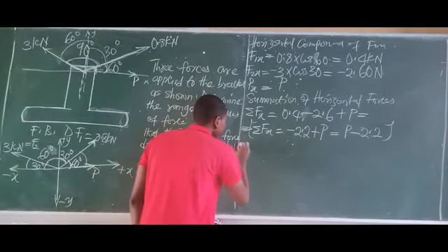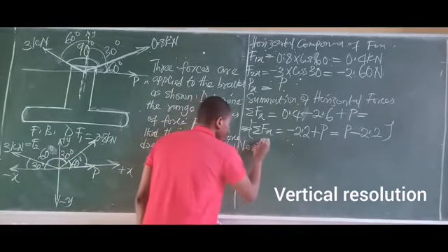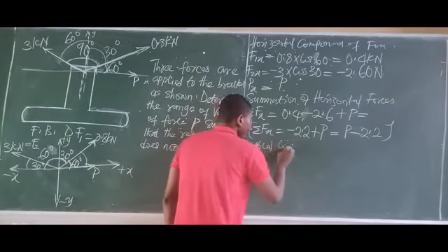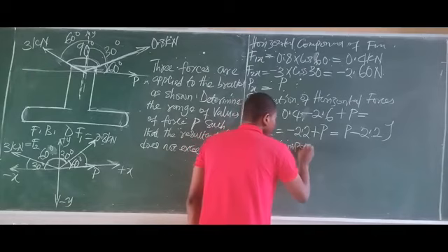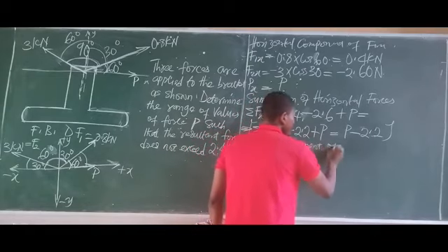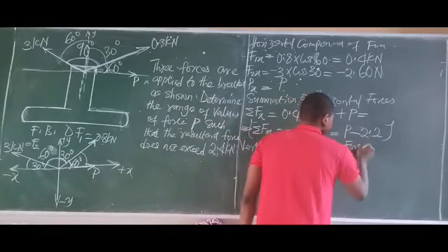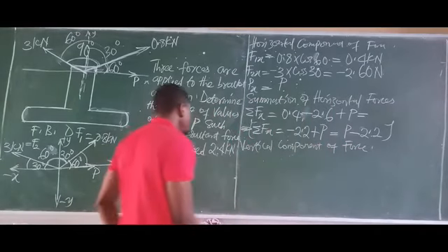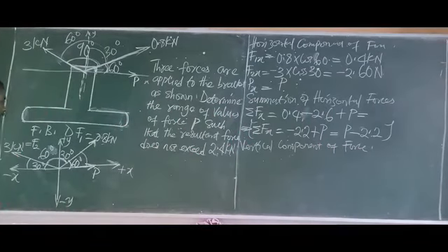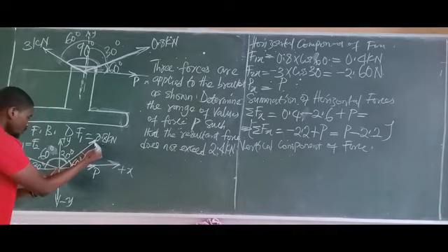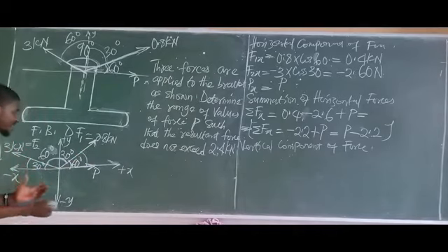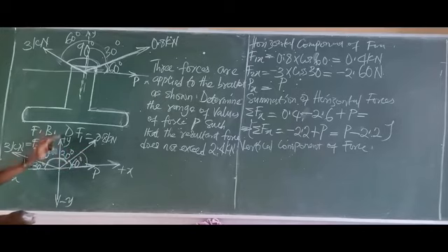Next is to find the vertical component of force. The same principle, the same idea. Hold the tip of the arrow of the force. Now you're pulling to the nearest vertical component in that quadrant, and the nearest vertical component is simply from the origin to this, and not the horizontal one, not the one beneath, sorry.